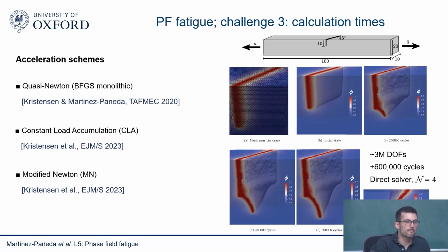But just having the degradation function for the phase field should be sufficient, right? Why do we still need the Chaboche kind of models for the constitutive model? Because you're already kind of saying, even for the constitutive model, it's all embedded into the degradation function.